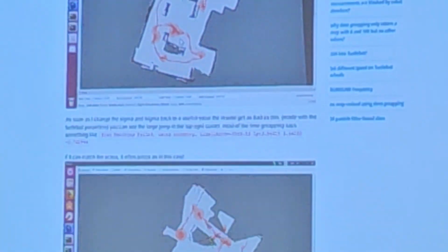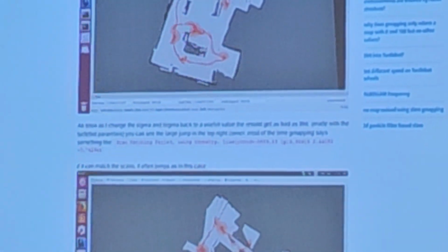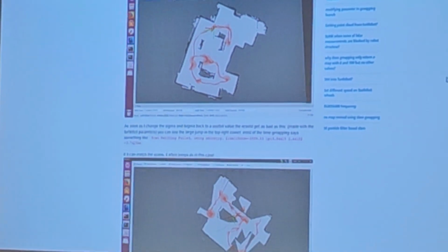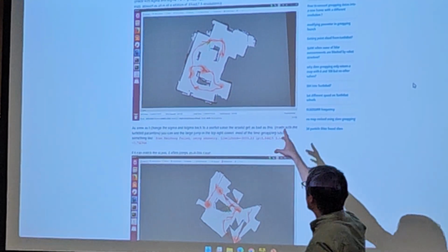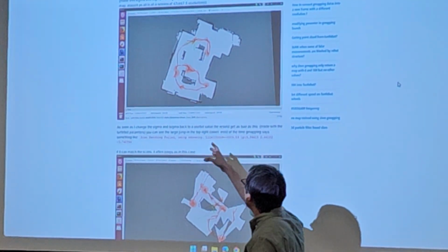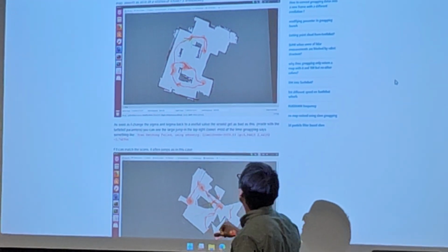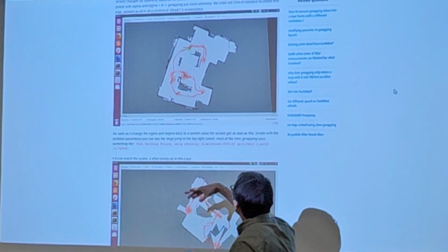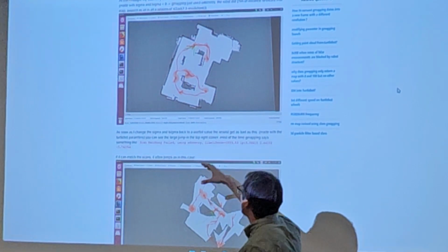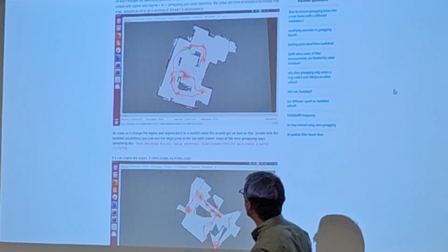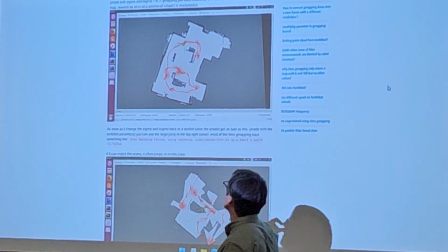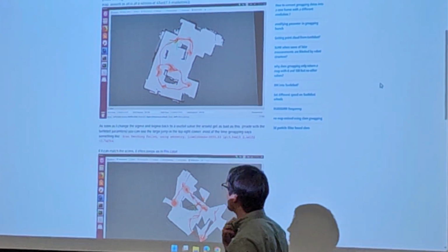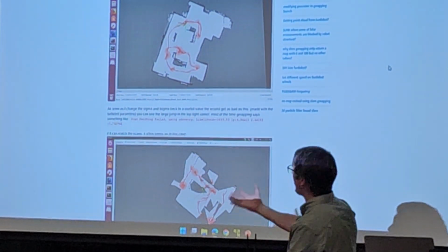So we can also see the robot as it's moved around in here. But what GMapping will do is it will generate a map like this. Using the laser scan, it will collect all the distances that it sees around it to build up what we call an occupancy grid. And then it will also track where it is in that environment, and these mapping algorithms are also tracking things that we refer to as landmarks in the environment.